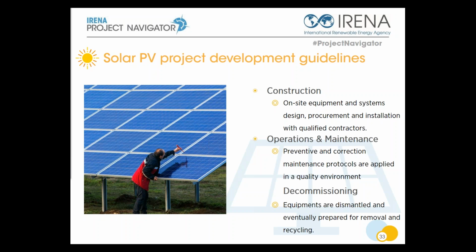So, for example, we provide recommendations on plant arrangement, plant optimization, dealing with soiling and shading issues. We also explain in simple terms the performance ratio questions, and also look at capacity factor, so how those values will in the end translate into financial returns.